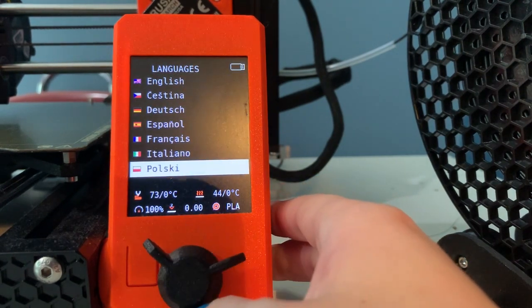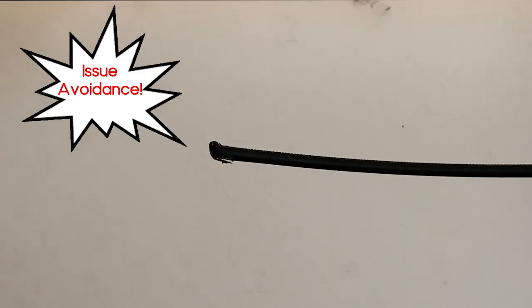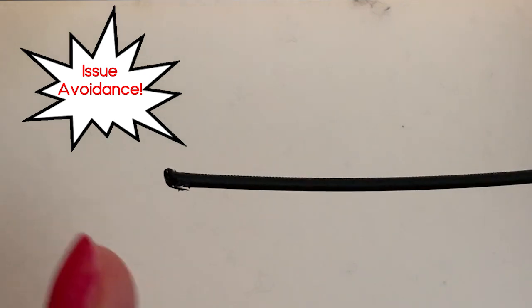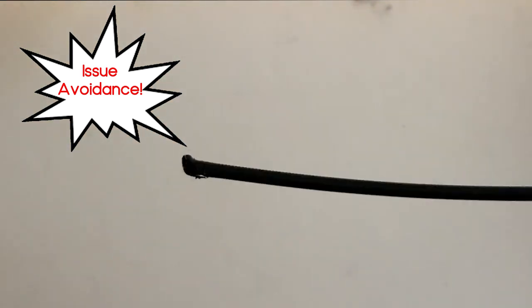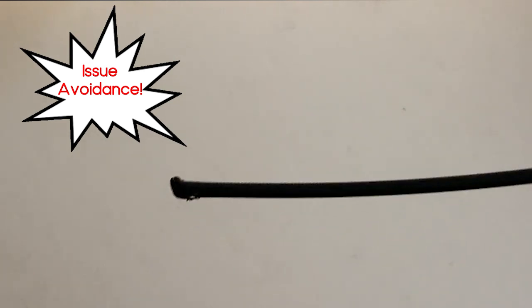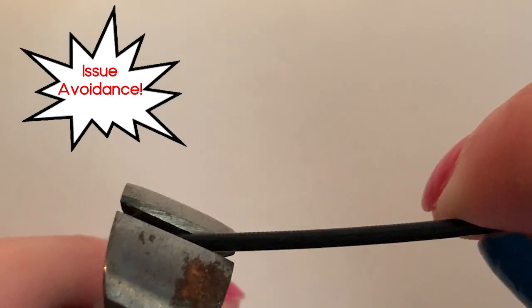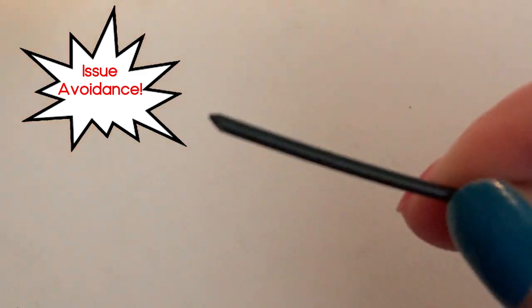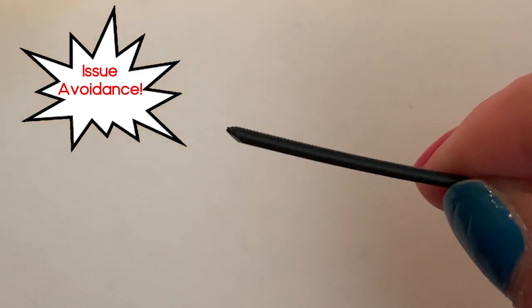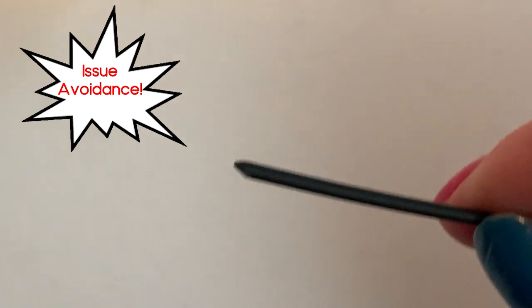Select your preferred language. Before loading your filament, one thing you need to look at is the tip of your filament. See how it's kind of ball-shaped? That might get caught on the extruder and might damage the printer. So the way to fix this is to cut the tip. So see now how the tip of the filament is sharp and ready to be extruded.